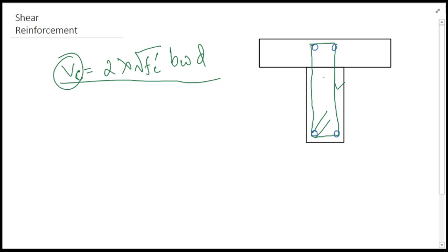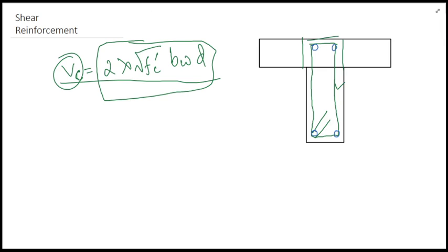This is the shear reinforcement, and other than that, this formula actually indicates nothing but the capacity of this concrete to bear the shear force. The bending force we have already calculated using flexural strength. But what about the shear stress? This shear force in this section will be acting like this as a whole.